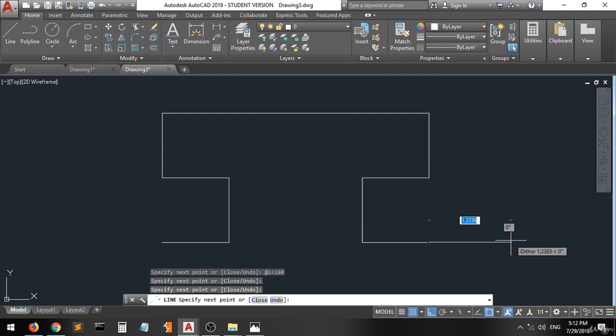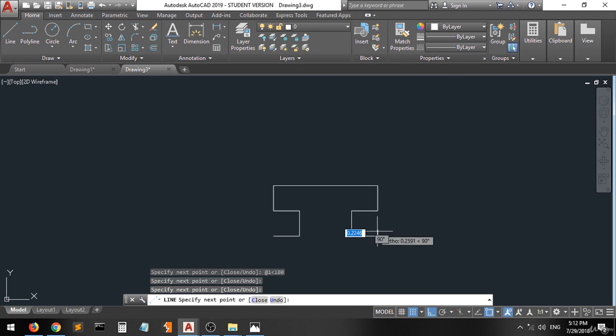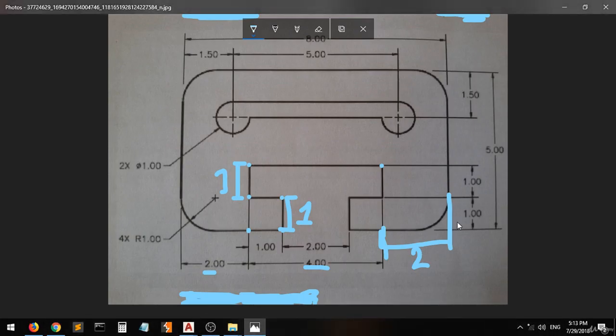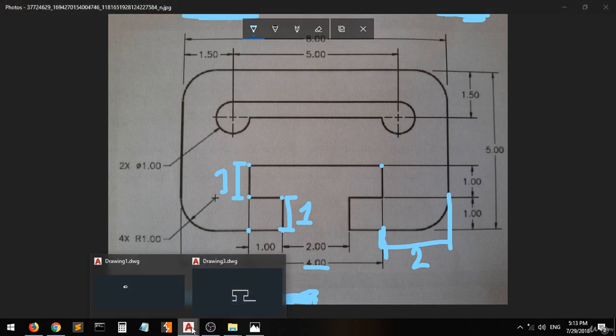So we'll move. Zoom back a little bit. We'll do 2 in the direction of 0. Excellent. Now, going back to the drawing, we will move this whole distance, which is 5. As we said, we will create it with a pointed head, then we'll create the fillet shape, okay? Don't forget this. We'll create it as a simple rectangle, then we'll do the fillet shapes, okay?